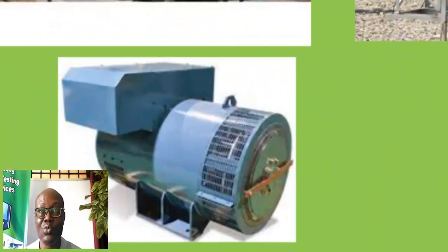Then on generators too, you can use them, but in this case, like we did in the insulation resistance test, you can test between winding and ground, or you can disconnect the start point and test between each winding. That is the U to V, V to W, and W to U, that is between the phases, and also between phase to ground. A general test between the winding and ground will give you an idea as to the insulation level of the insulators used to separate the windings from ground in the alternator. But that will not give you the health of the insulation that is separating each of the windings. So for you to know that, you have to disconnect the start point and then carry out the power factor test between the phases.